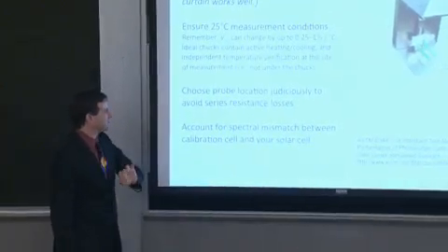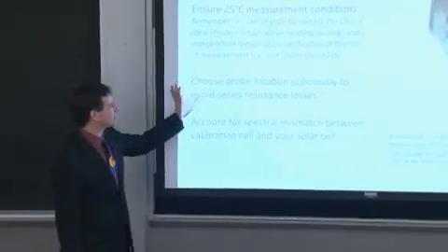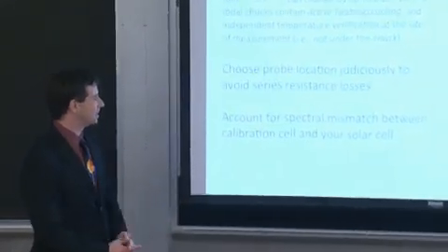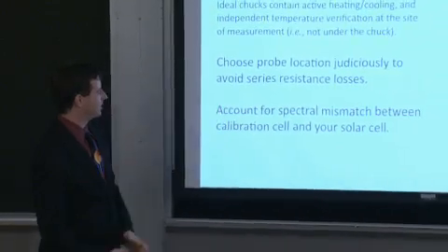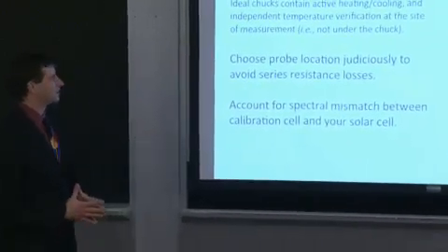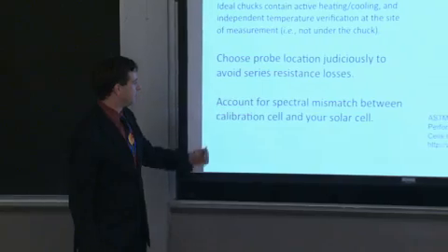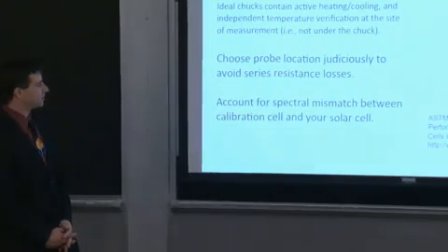I don't want to underemphasize that point. It really does make a huge difference where you put your probe tips, especially for cells with high series resistance, which can be several of the new materials that are being developed. Account for spectral mismatch between calibration cell and your cell.